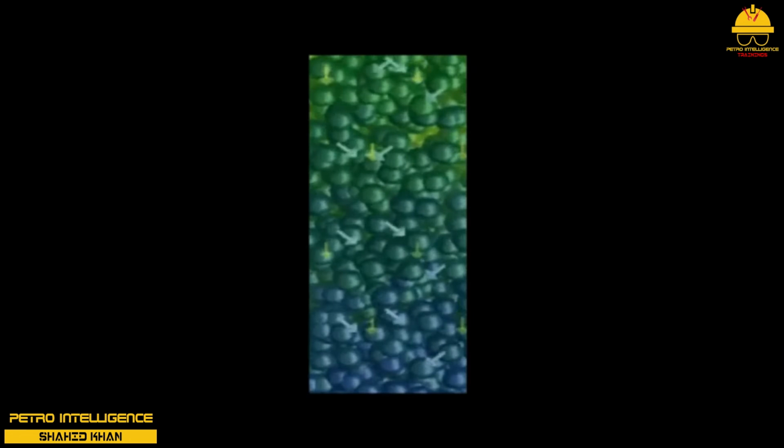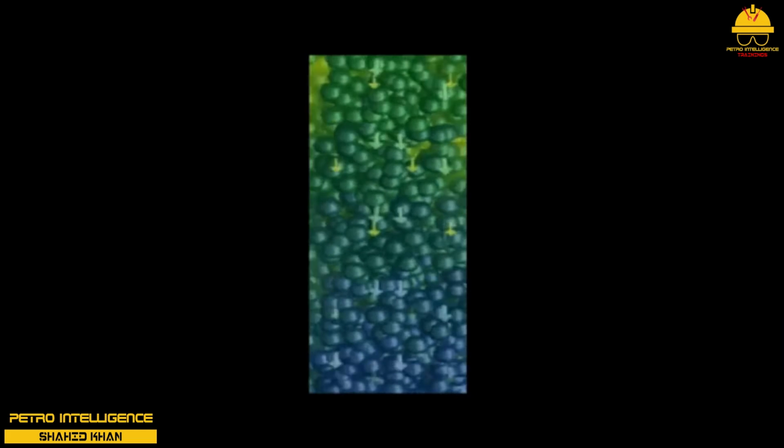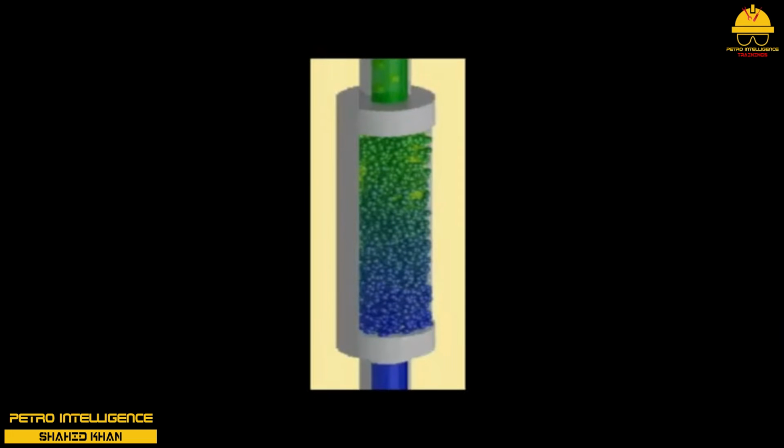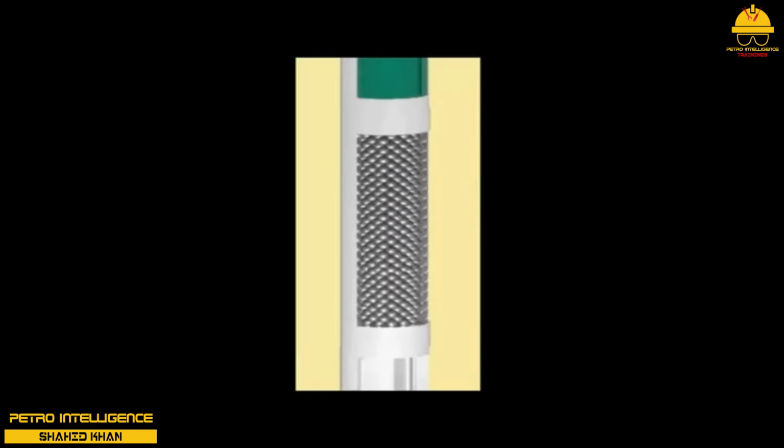The bed of packing, whether catalyst or inert particles, is positioned in the direct path of the process flow and can be arranged as a single large bed, as several horizontal beds supported on trays, or as several beds, each in its own shell. It can also be in several parallel packed tubes in a single shell. As the process medium passes through the catalyst, the reaction occurs. Since the catalyst occupies a fixed position inside the reactor, it is not designed to leave the reactor with the